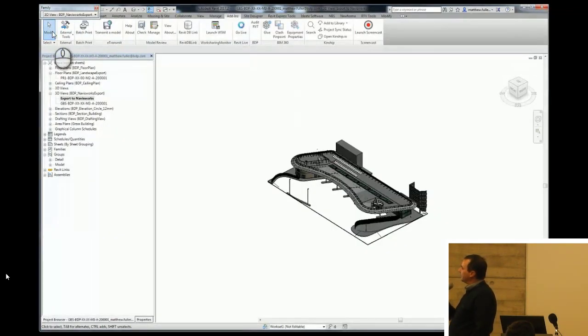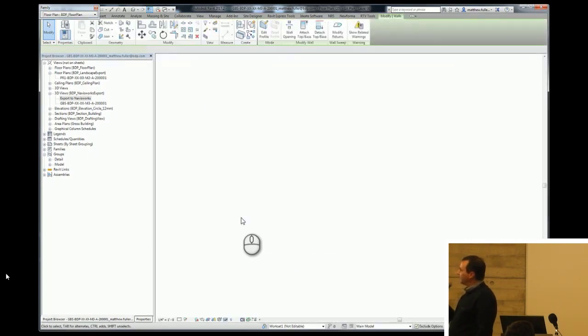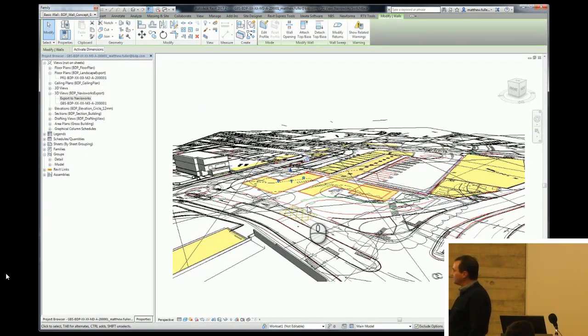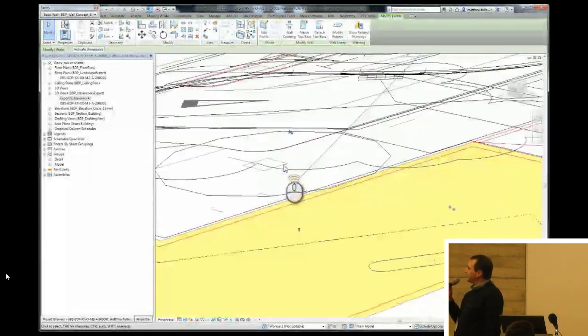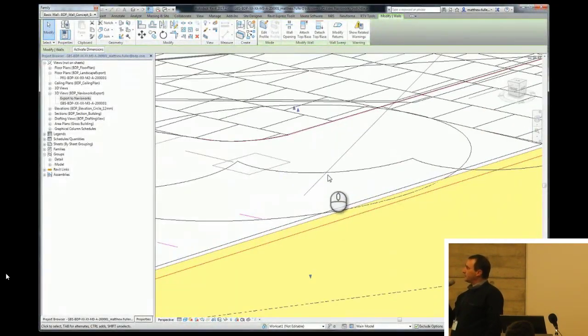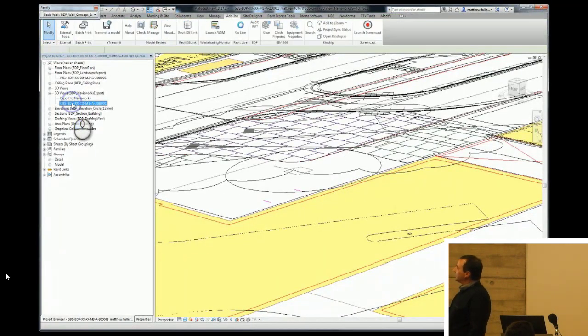So with your element selected, you click on switchback, it will jump back to Revit, and it will find you a view with those elements in, and usually it's a rubbish view. So the next tip is, don't click on anything, leave your object selected, go to a view that you know and trust, and use the section box tool.